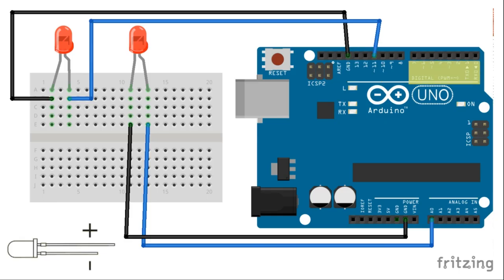So on the screen you can see where I'm pointing the cursor over here. You can see that the tilde notation stands for pulse width modulation, so only pins 3, 5, 6, 9, 10, 11 support pulse width modulation, and this is exposed through the method analogWrite. Even though the method is named analogWrite, it has nothing to do with analogRead or the analog pins, where I'm pointing with the cursor at the moment, the 6 analog pins on the bottom right of the screen. This distinction confuses some people most of the time, so be aware of that.